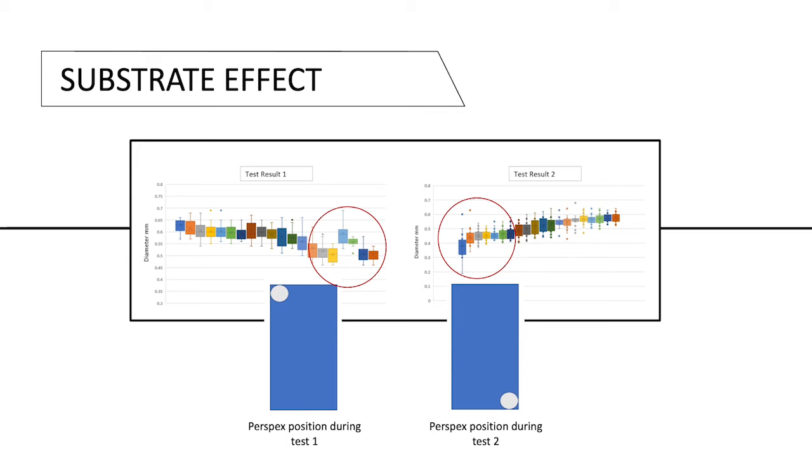In this case, we found even with optimized dispensing parameters, small factors like flatness of the substrate, the dispensing pressure, the needle tip, all had significant impact on dotting repeatability of the same silver-filled epoxy with the same dispensing system.